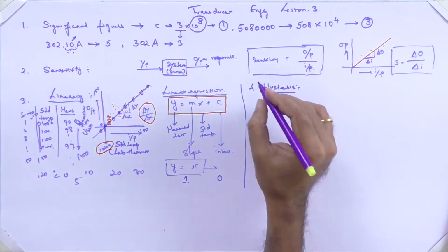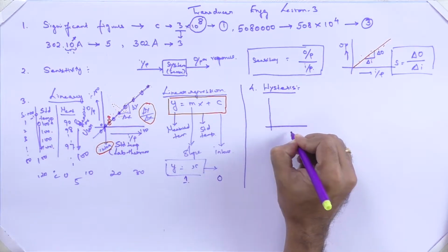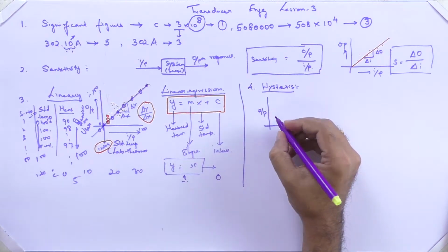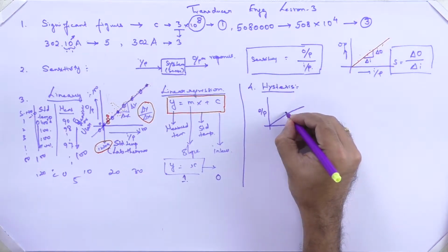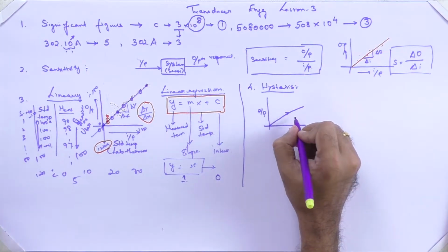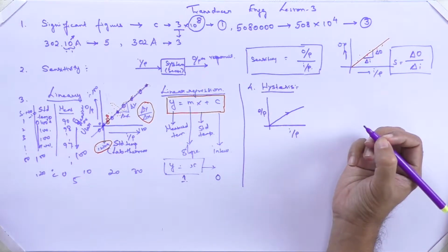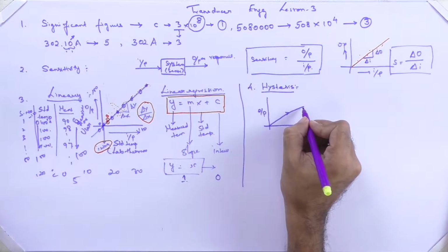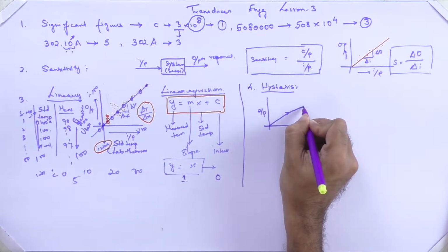The hysteresis model is one which shows that when you give an input to a system and we get the output from the system, both won't be in a linear relationship. For that linearity only I explained it. Now we will see how it behaves. We are giving an input to the system. Let us imagine it is an ideal linear condition, it is increasing. We are loading the system with some input, then it's unloaded.